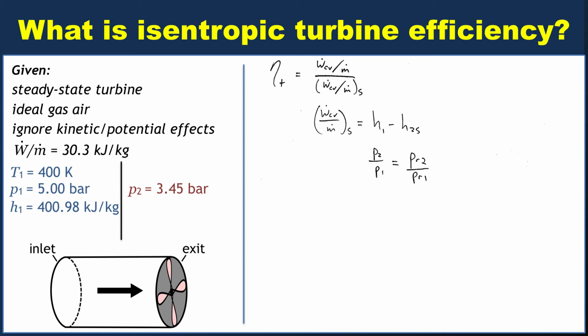I note this in the lecture notes explicitly in bold. They don't have units of pressure. They are in fact unitless. They're exponentials, so that means they're unitless automatically, and they involve the s degree functions, so it's kind of a complicated thing. The reason you get this simple ratio is that you go through and do all the stuff that we already know about an ideal gas, consider an isentropic case, and you can derive these very simple ratios because we've sort of subsumed all the complexity into this PR variable that you can just look up in a table.